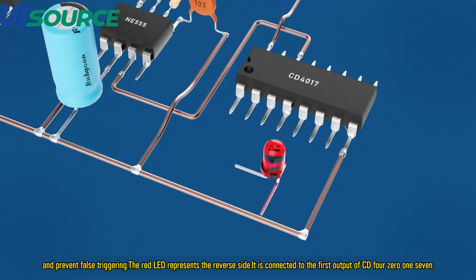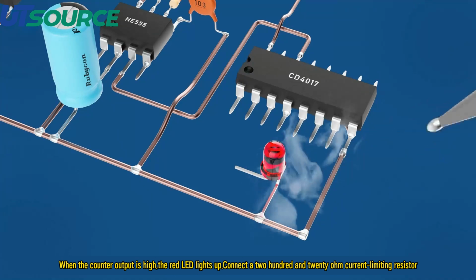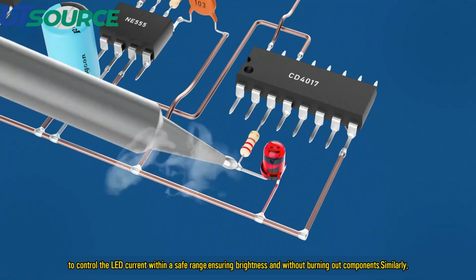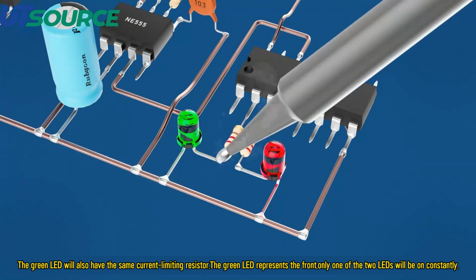The red LED represents the reverse side. It is connected to the first output of the CD4017. When the counter output is high, the red LED lights up, connected to a 120 ohm current limiting resistor to control the LED current within a safe range, ensuring brightness without burning out components. Similarly, the green LED will also have the same current limiting resistor. The green LED represents the front. Only one of the 2 LEDs will be on constantly, randomly displaying the result of the coin toss.